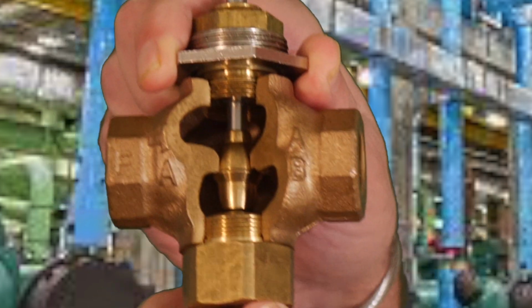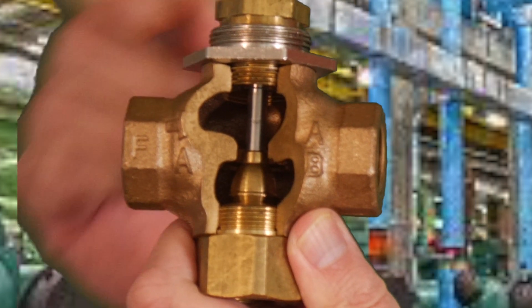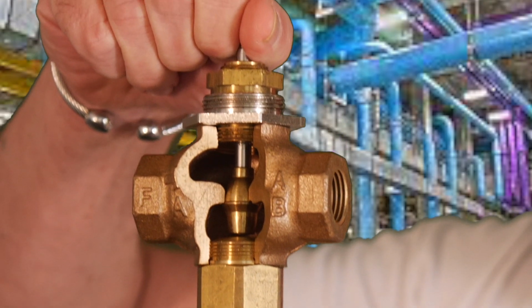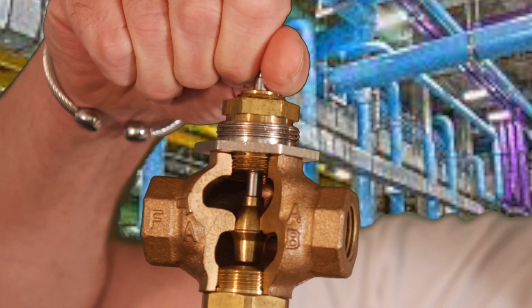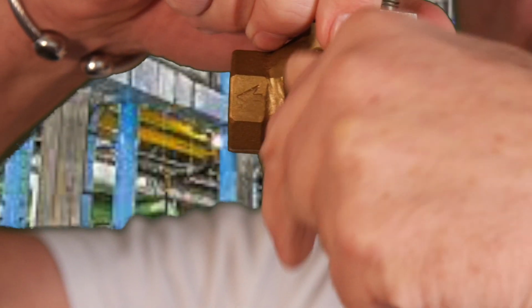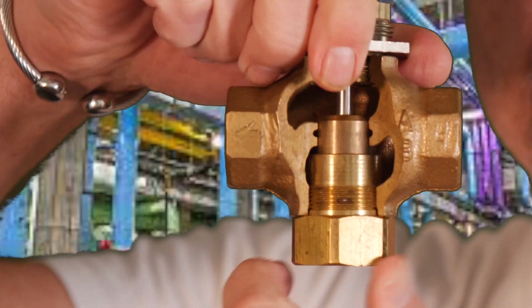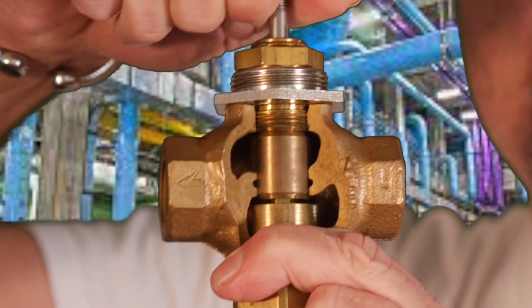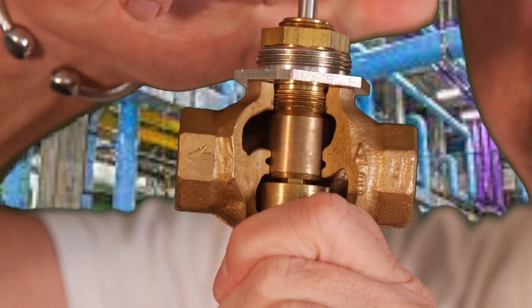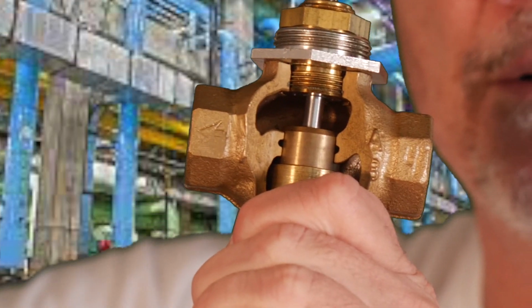All right, as you can see, as this thing lifts up, the actuator pulls up, you're going to go from this port to this port out this way as the actuator lifts up. As it goes down, you're going to go straight through the pattern, as you can see here. Now you're going from here out here, and anywhere in between, you're actually mixing or blending. So here's your diverting valve, okay? So here's your AB port right here. Here's your B port, and you go through A here. So as you can see, by this particular valve's designation, your flow is going to either go here or it's going to go here. Okay, one in, two outs. And as you can see, as this pulls up, now you're going from here through here. As the actuator pushes down, you're going from here to here.